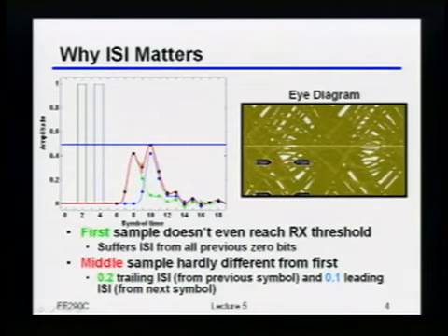Okay? So anytime you have this dispersion like this, what it means to spread those pulses out is that if you try to do things that are changing very quickly, then you don't actually get the changes you want. Okay? You see things that are smeared out and look very flat, even though you were trying to change them quickly. Okay? So again, the point is that you care about this because you can see in this particular example, I've made the ISI so bad that I will completely not receive the bits at all. Right? All three of these would be decoded as 0, even though they're supposed to be 1s.